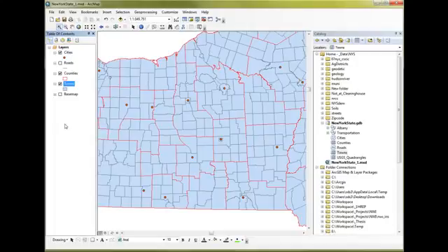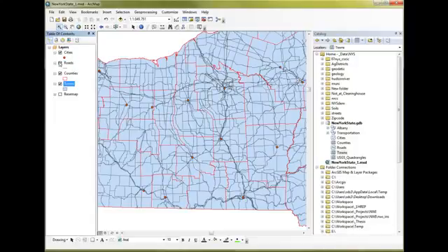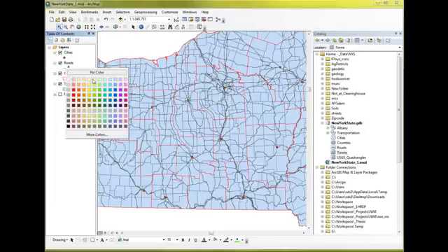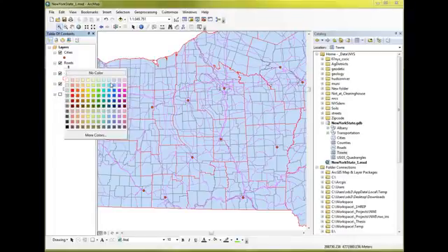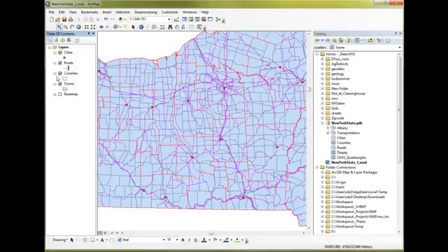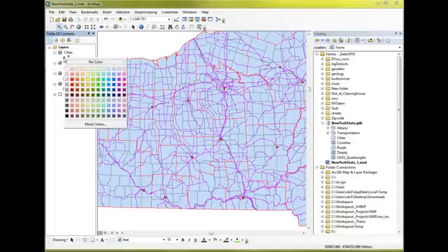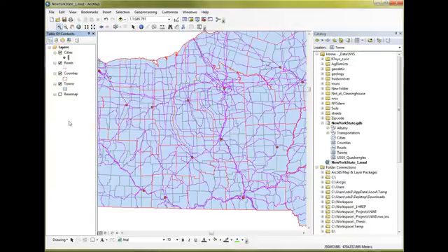So now we have towns, we have the county layer laying on top of it as a hollow polygon, we have the road layer we can add in there, and we have cities. Maybe we should change the road color yet again. The way, again, I'm changing those colors is just to right click on the symbol and I get a little color palette I can pick and choose from. There's much more in symbology we can get into, and we will later.